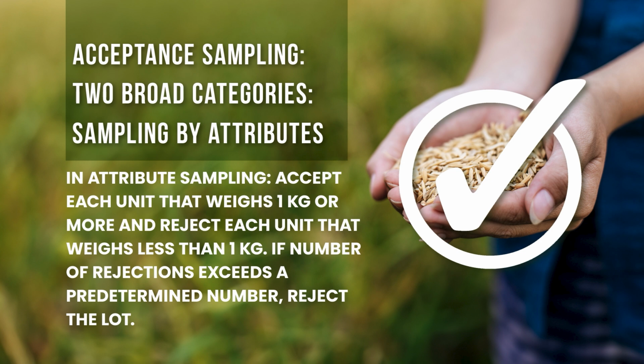Arsenic in water is variable sampling. We know very well, and this point I must emphasize very clearly, that arsenic in water is present, widespread contamination of groundwater with arsenic. Now, can we afford to have attribute sampling for arsenic in water? Certainly not. So in those cases, we don't follow the attribute sampling. We follow the variable sampling.